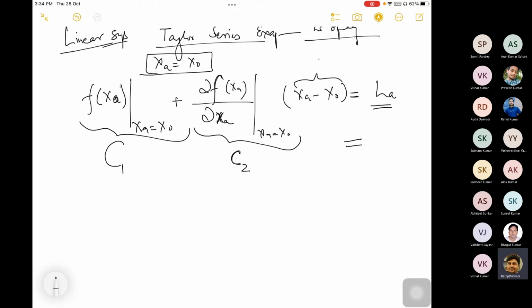This would be delta X. If you multiply the individual components, one with this and another with this, you will get a whole multiplicative picture. But for the time being, we are just using this as delta X, C2 delta X. On the right hand side, as I told you, la is written as lb plus v. This is a correction or residual that is applied to the raw observation, and only then will you achieve the adjusted value. So la is nothing but lb plus v. v could be positive or negative; that would come out after finding the solution.